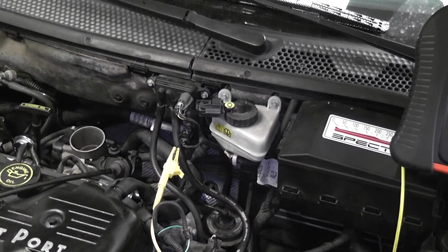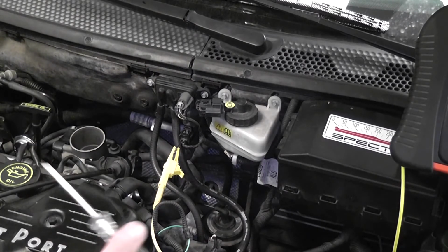This will be a complete test other than the driver. So we're checking everything in the system with this except for the computer driver. It's a ground side switch circuit. We're going to take a test light to ground and we're going to ground the control wire, quote, being the computer, grounding the circuit. If this solenoid functions, the RPM should get real rough. The DPFE voltage should rise.